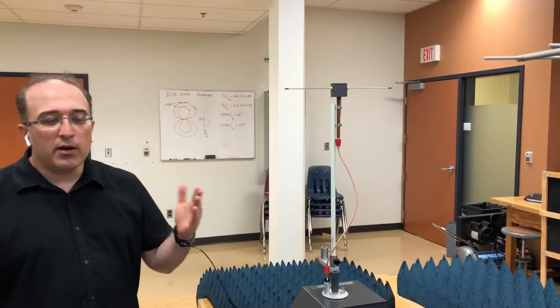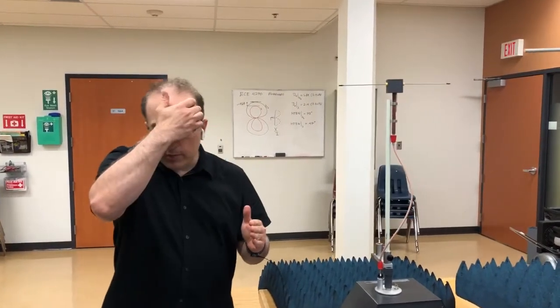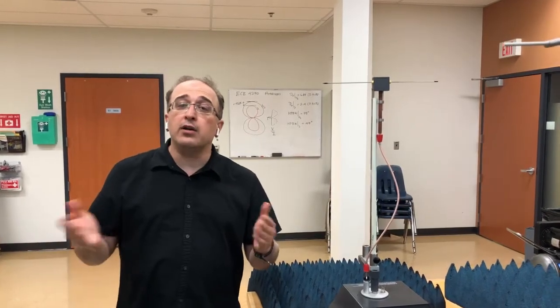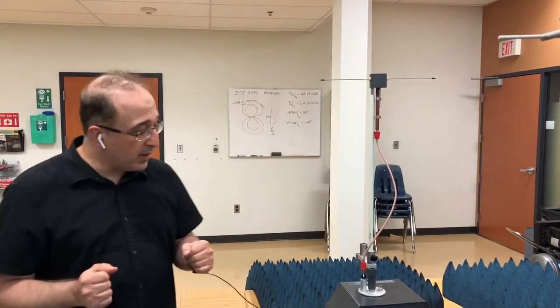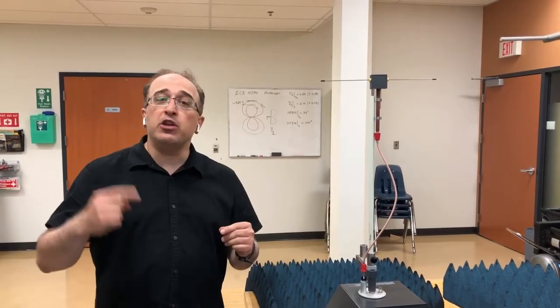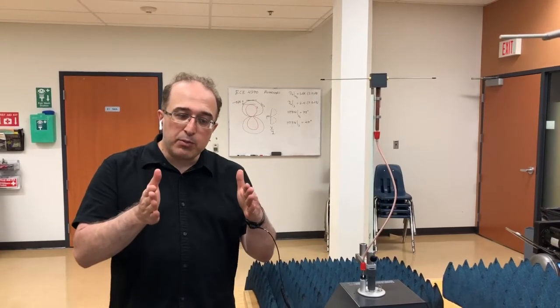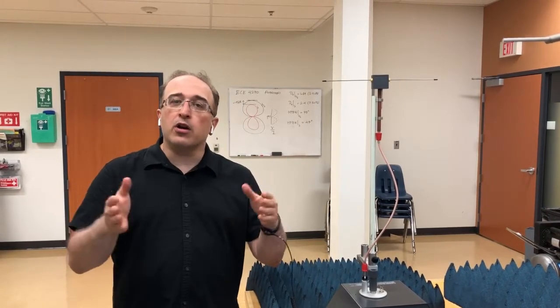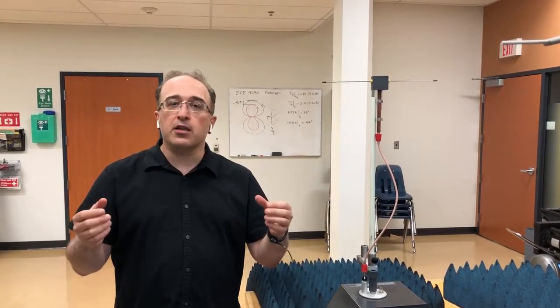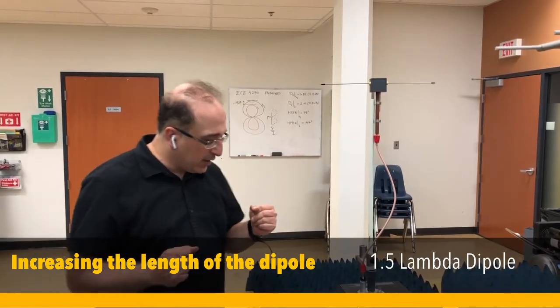Okay, so we saw that we increased the length of the dipole from half a wavelength to 1 lambda. So we went from lambda divided by 2 to lambda, and now we're going to increase it beyond lambda. We know from the course that if you increase it beyond lambda, you're going to start having out of phase currents on the dipole antenna. That is what we want to study right now.